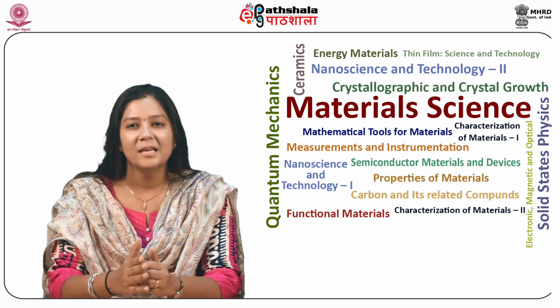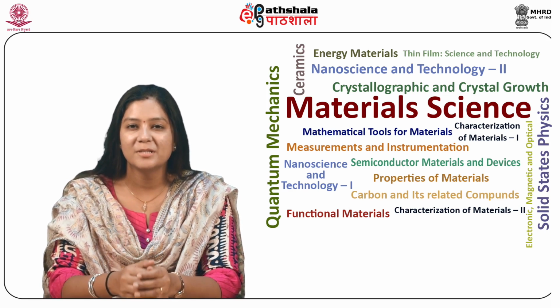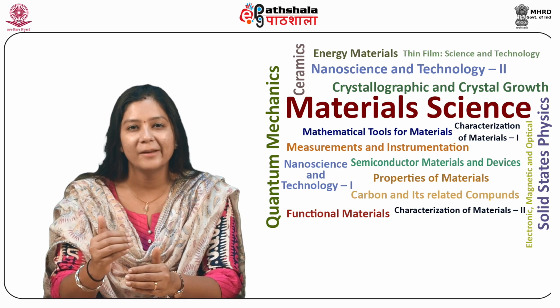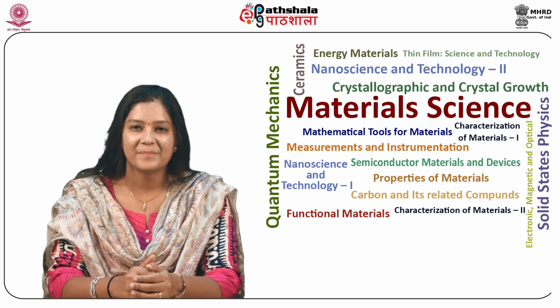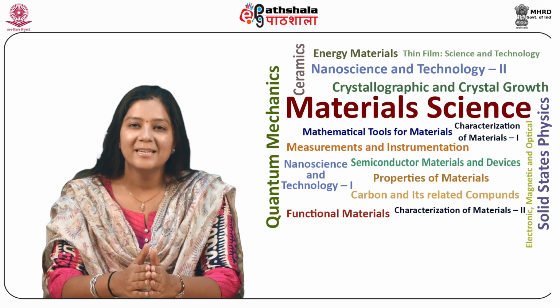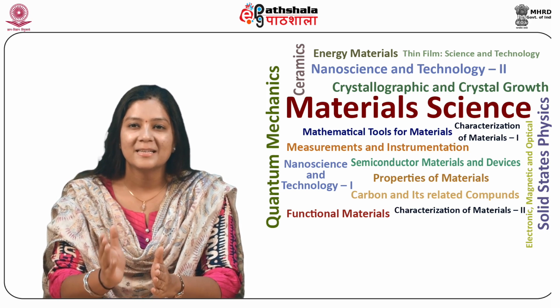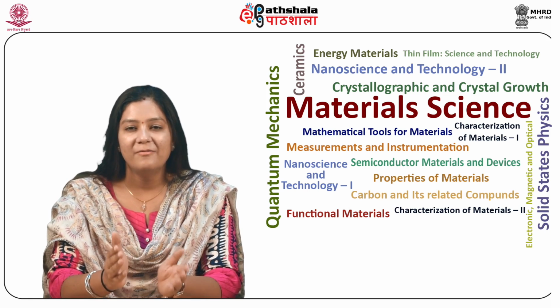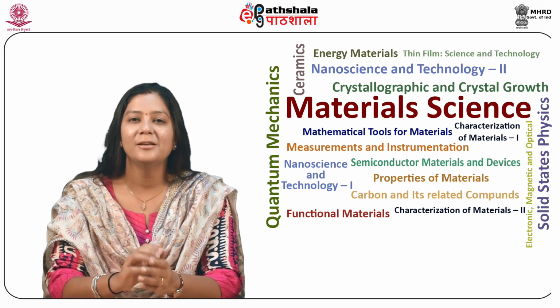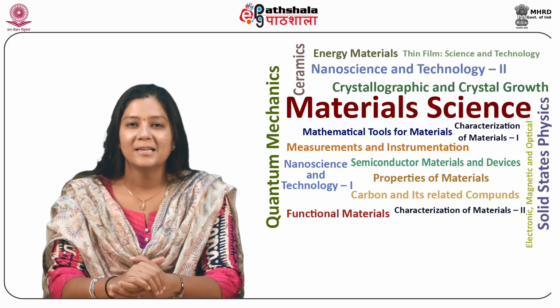Bulk micromachining as well as surface micromachining is used to develop microstructures onto the surface of these MEMS devices. Bulk micromachining mostly utilizes wet etching techniques for fabricating microstructures, whereas surface micromachining uses dry etching techniques.